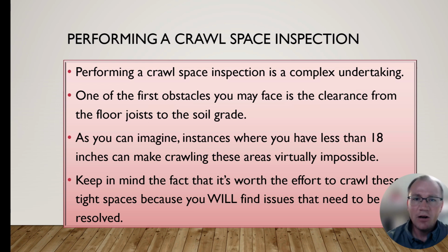And I tell people this all the time, it's very important to get in these crawl spaces because if you don't, you're not really taking care of your customer. The fact of the matter is that they can be very tight. I've even had instances where we had to dig our way through a crawl space, move soil and different things. But that's where you're going to find the major problems, especially as we're going to talk later about moisture issues. The closer the floor joists are to the soil, the more problems there can be. So I do understand if it's less than 18 inches, especially, it can be really tough to crawl. But you really want to get underneath there. It's going to be good for your business, good for the customer, and everybody's going to win.